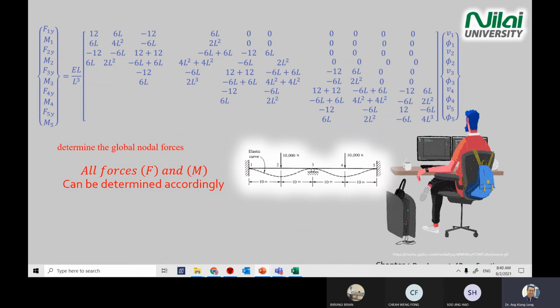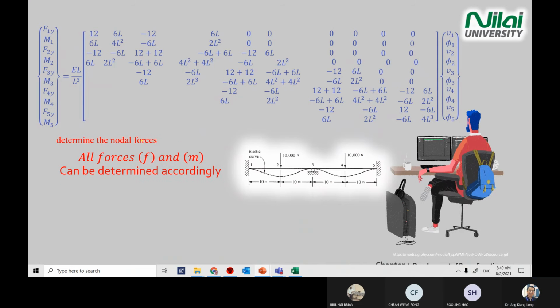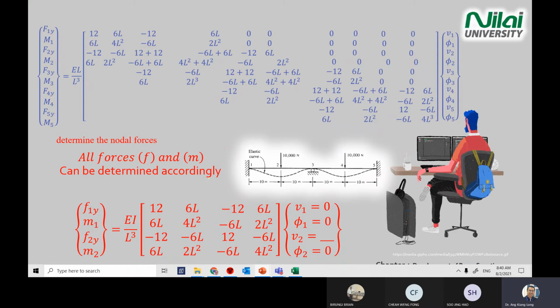After you solve for the individual element, for example, this one is the element, small f is the element. You write the first element. When you write the element, don't confuse, don't straight away use the global matrix. You have to go to the element matrix where the small k value is equal to this one, not the one that you see over here.